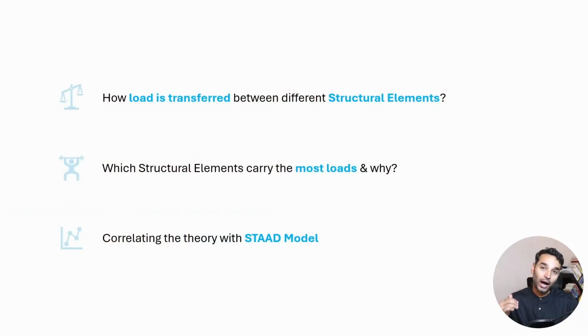In this video, we'll be learning about the load transfer mechanism, and how the loads are transferred between different structural elements, which structural elements carry the most loads and why. This will give you an insight as to how you should be designing different structural elements of varying strengths. And finally, we'll be correlating all the things we're talking about with a STAAD model.